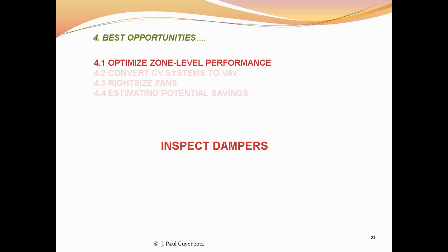And the testing and balancing contractor measures the air that's being actually delivered to the spaces. And then there are dampers that have been incorporated into the duct system, and he adjusts those to get the right amount of air delivered to each space. Periodically inspecting the dampers and their linkages for proper operation is